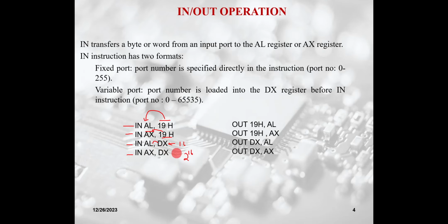So these are input output ports. Similarly, when I write AX, some of these 2 to the power of 16 ports could be 8-bit ports. So whenever it's an 8-bit port, I can write IN AL, DX, and if it is a 16-bit port, 2 bytes of information can be simultaneously read into the AX register from that specific port. So this is the IN command.